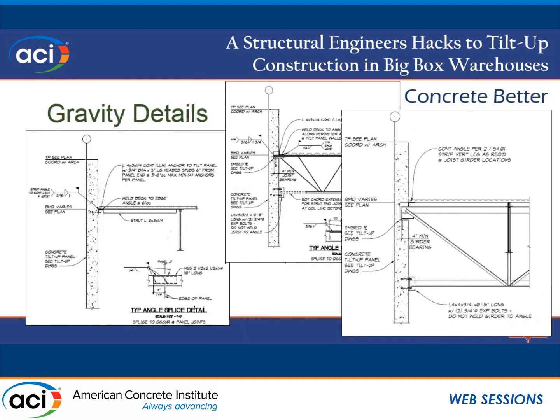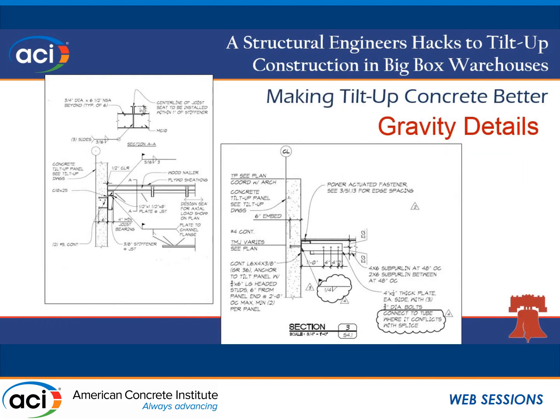You'll notice on this one I have struts. We like to use struts for the deck bearing side. I think it's a more constructible detail. Gives you a little bit of redundancy too as a structural engineer. I like redundancy. For your hybrid wood roofs, account for your out-of-plane loads, your sub-diaphragm action. Make sure you also have a good load path for your in-plane loads.